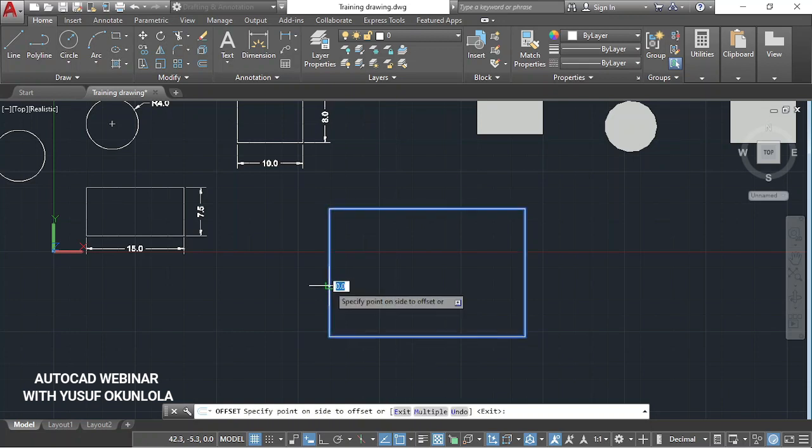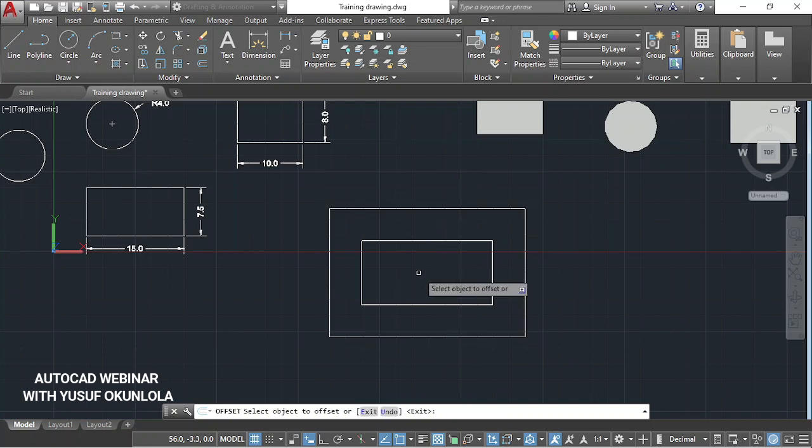So I'll click on this rectangle, and then you see that we have another replica of this rectangle internally here, and once I click on enter, you can see a new rectangle inside. I'm sure if we've done technical drawing, we usually draw a borderline and stuff like that, so I won't go into much detail here. So on AutoCAD you can just decide to use this offset tool.